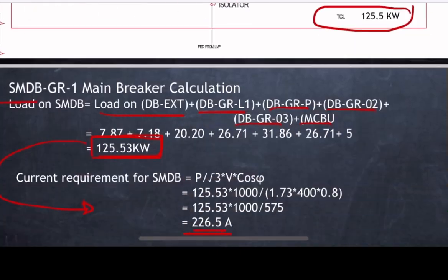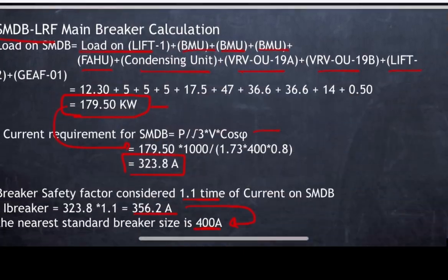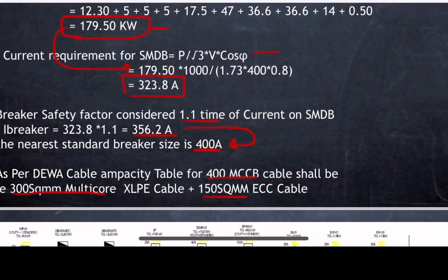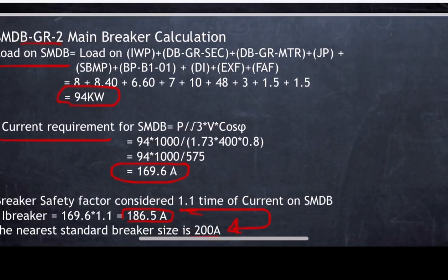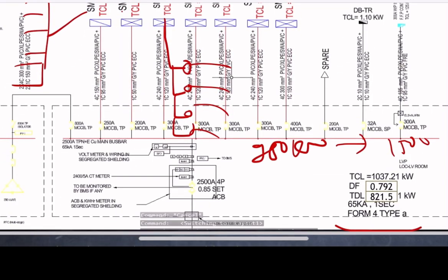The second point, as I told you, is that the fire pump will start during the fire condition, and in the fire condition most of the AC load will be shut down. That is why we can go for the first case, that is, we can choose a 1500 kVA transformer for a load from 801 kilowatt to 1200 kilowatt. Hope you are clear so far.